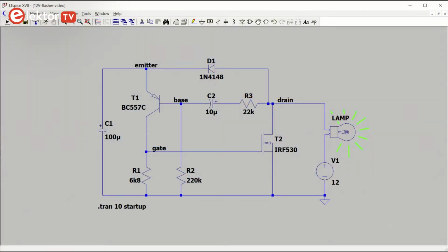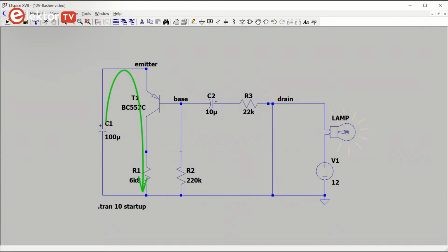The voltage on the drain of T2 is now almost 0 volts and diode D1 has become reverse biased and no longer conducts. Because D1 now blocks, C1 no longer gets power and starts to discharge, mainly through R1. Another discharge path is through the base of T1 through C2 and R3, and the third is through the base of T1 and R2. Because C1 has become the power supply of the circuit and is being discharged, the voltages in the circuit all drop together, keeping T1 in conduction.